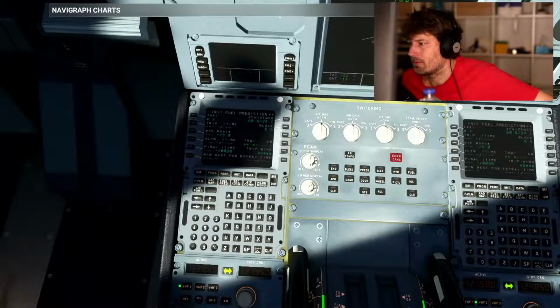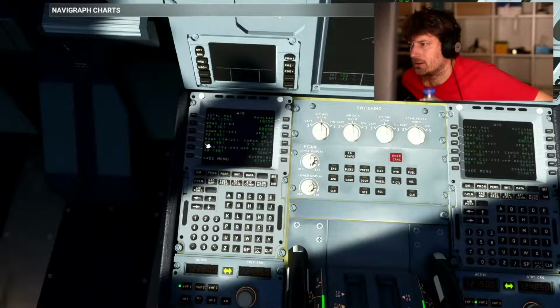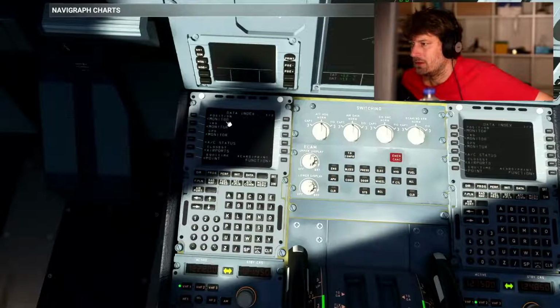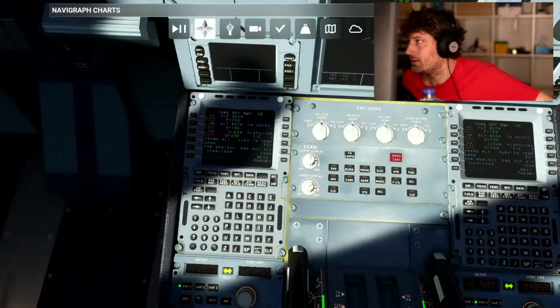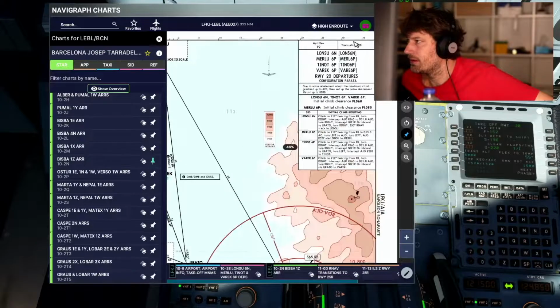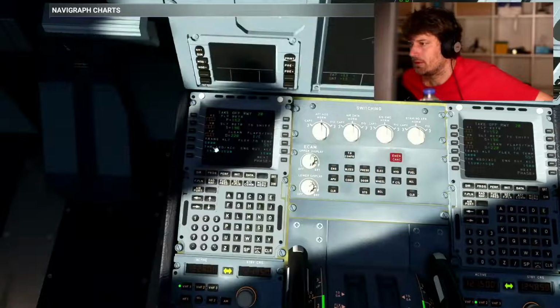Let's have a look again at the weight and balance here. If the passengers are all on board now, they are. And luckily the CG went back to 24.1. Good. Performance page, flaps 1, takeoff, 55 max temperature, transition altitude. What's the transition altitude here? 5,000 feet. So that's correct. And then we can calculate V1, rotate, and V2.